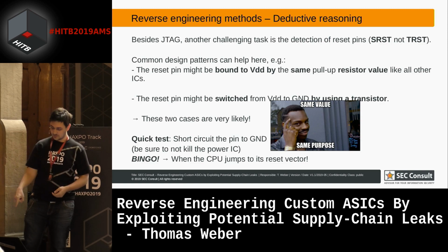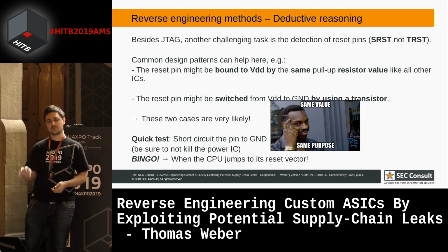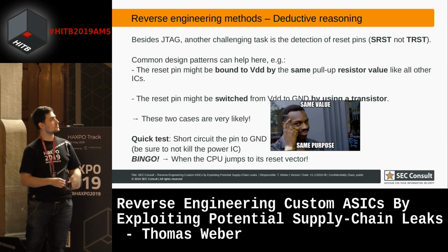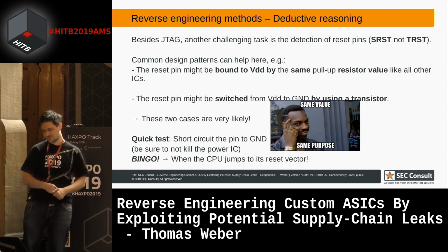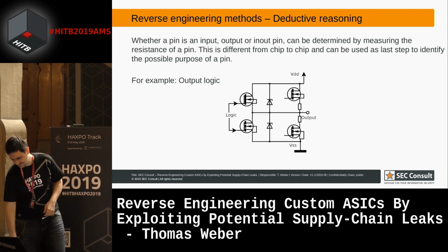So on the actual device, when you remove a transistor on the backside, it actually works, but you can use the system reset. And yeah, that's really funny. The easy probe is just to short circuit the suspected reset pin to ground. And when it lights up or is completely dark or just stops what it is doing, then you can be sure that's reset. But yeah, be careful that you don't kill your device.